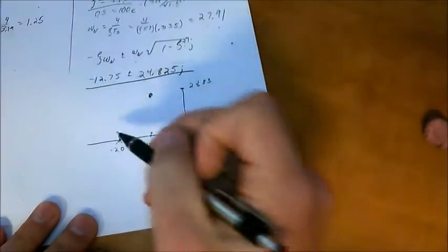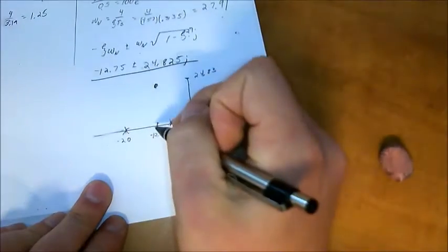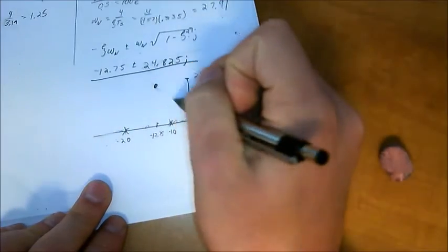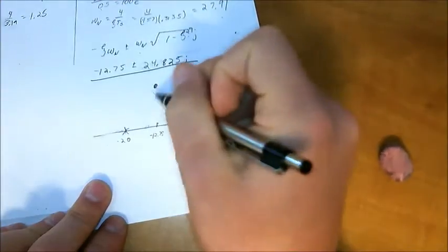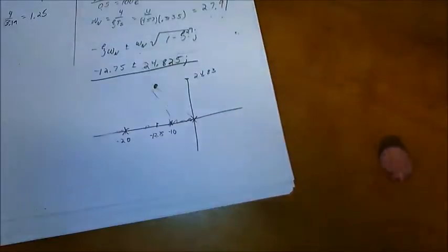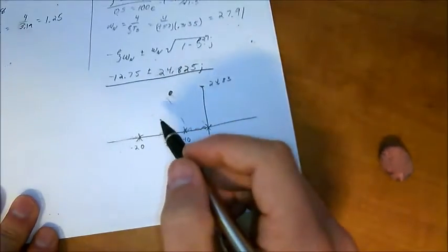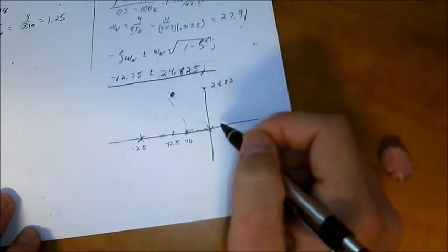And if we do our root locus, it's going to be something like that. Actually, it's not going to be something like that. We're going to have a 0 somewhere along this line, and we're able to use the angles of each one of these to find what that 0 is going to be now. We need to figure out what these angles are.